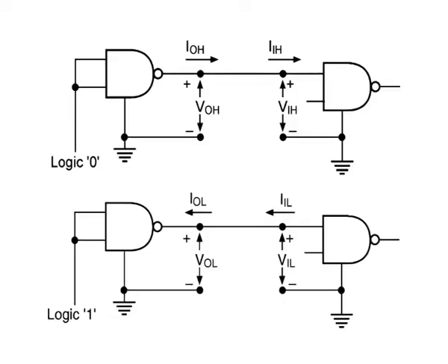High level output voltage. This is the minimum voltage on the output pin of a logic function when the input conditions establish logic high at the output for the specified family. In the case of the standard TTL family of devices, the high level output voltage can be as low as 2.4 volt and still be treated as a legal high logic state.